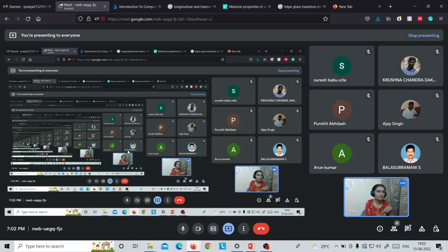There's also PEEK, but most of them involve epoxy constituents because you need to form permanent covalent bonds. So you need to have unstable rings within themselves so that they'll readily start cross-linking as soon as hardener is mixed. Fine. As such, there is no hard and fast rule. You just have to see the chemistry. Fine. Okay.